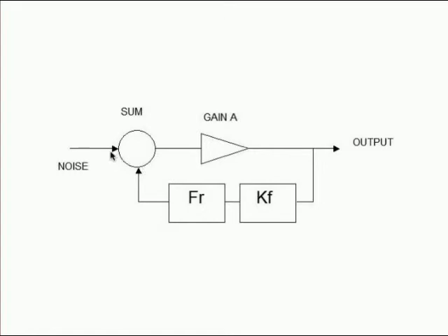So if we didn't have an input signal, then the loop gain is 1 because these two signals are equal. Now this signal is the combination of two signals, so we can see that the loop gain is going to be not exactly 1, it's going to be 0.9999 recurring, because this signal has got an input added to it. So the loop gain is very close to 1, but slightly less than 1.